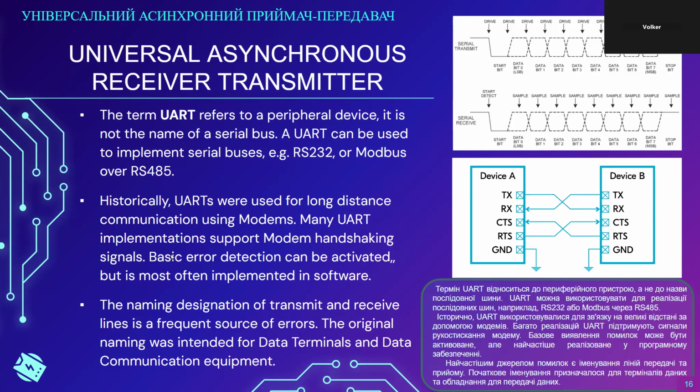That is another method of error detection, but it's a very primitive method because a checksum will just add up all the characters of one line and basically sum it up and turn it into a byte. And it will only, it usually detects single bit errors.